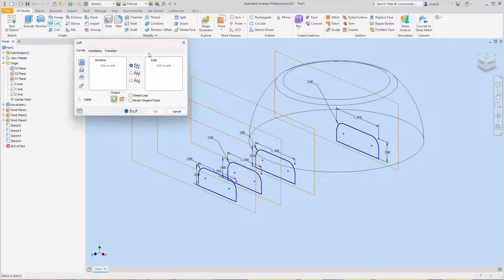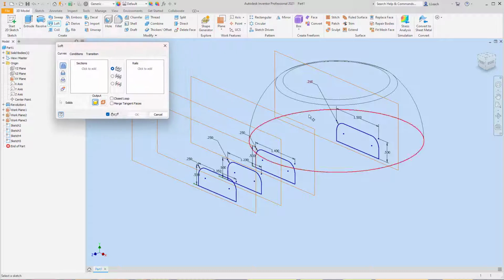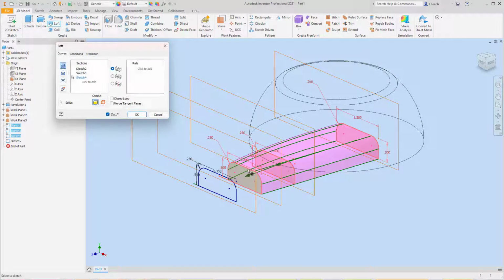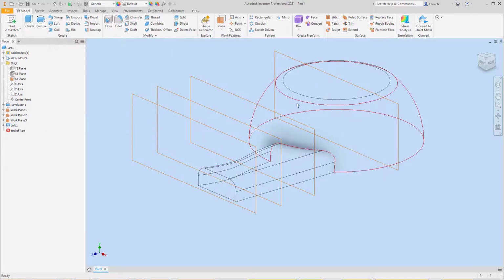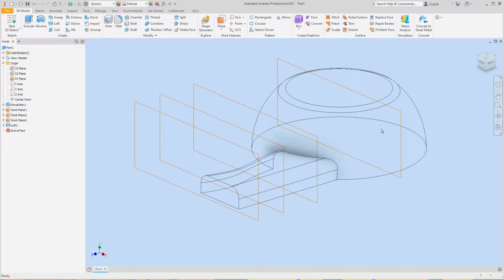And then, so I'm just gonna click the sketches. So I'm gonna click this back one first, click that one, click the second one, click the third one, click the last one. You kind of see it extrudes those shapes to where they merge together. And then I'm gonna hit the OK button here. So that's kind of neat. So yeah, that's creating the handle of our dryer housing.